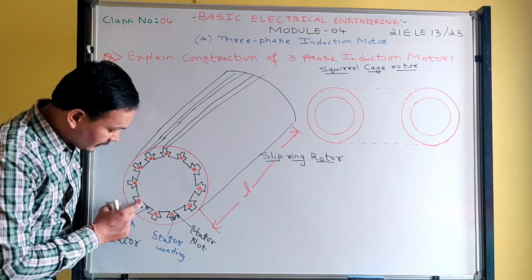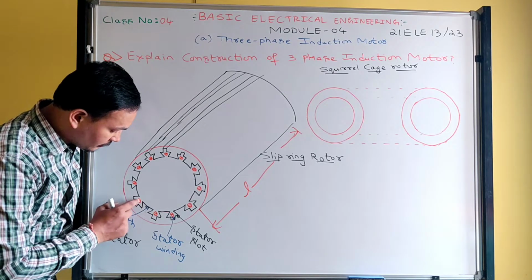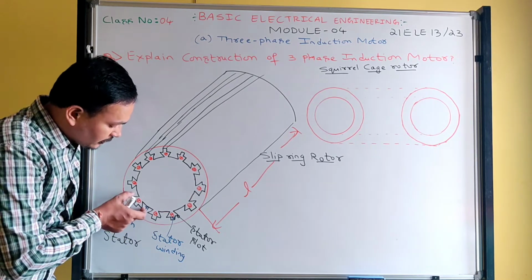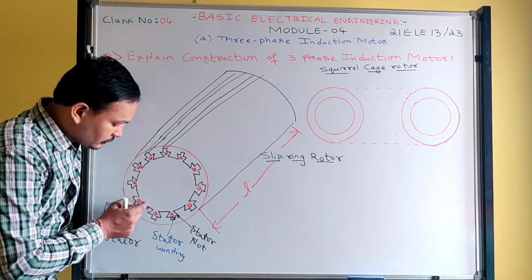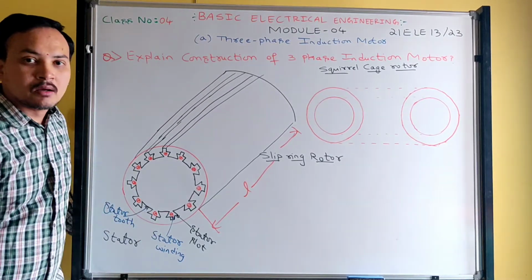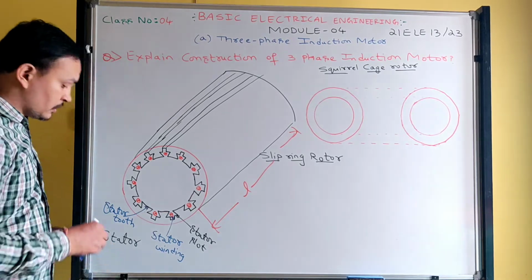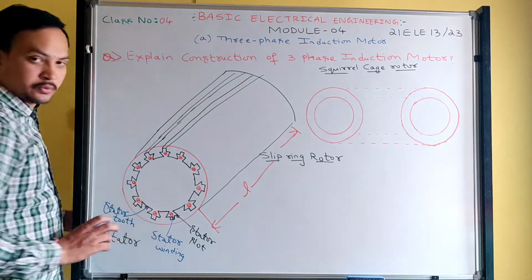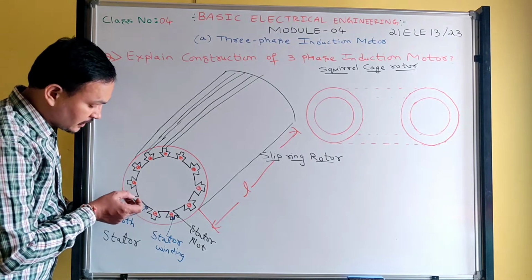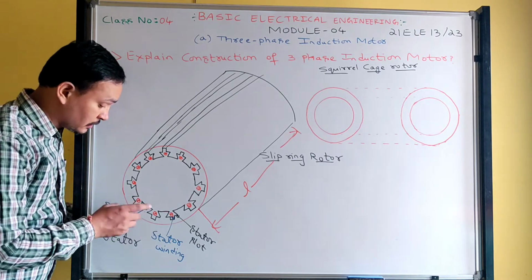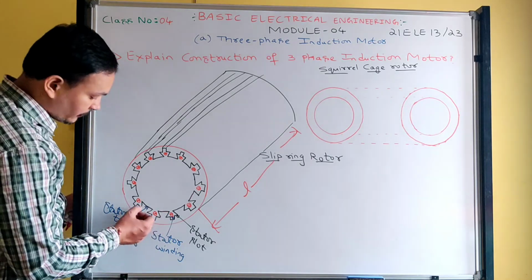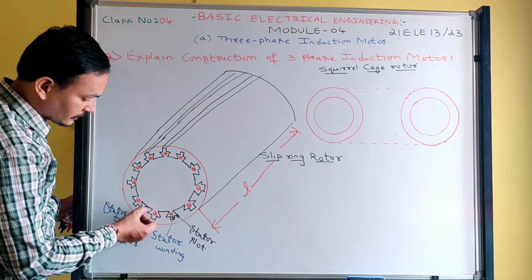See, if I make it wedge shaped, this conductor will not come away from the slot. Okay, to provide wedge shaped lamination, we need to do like this. So that provides a mechanical balance. Got it? So that is the function of the stator tooth, only for balance purpose, to make this slot in such a way that once we put the conductors in the slot, the conductor should not come away from the slot. So for that purpose, we need an extra construction like this.